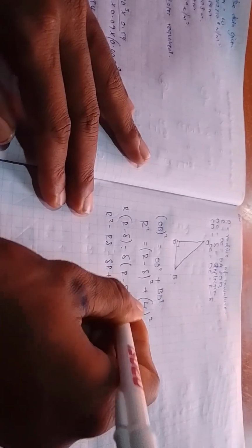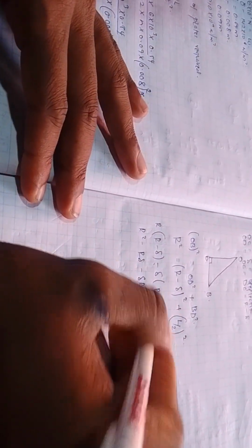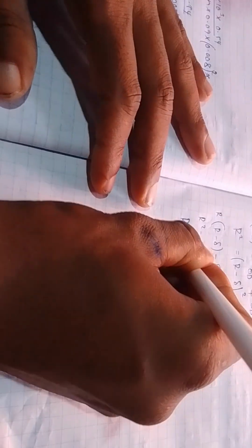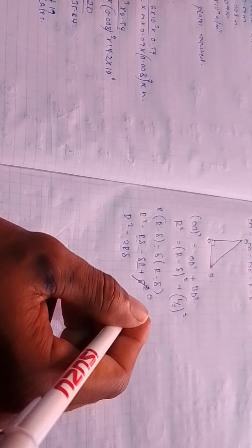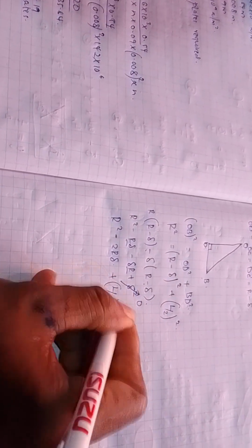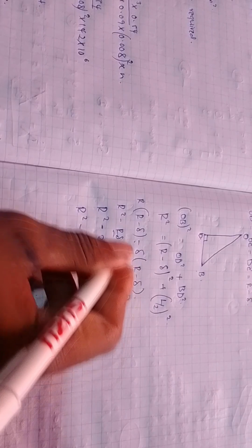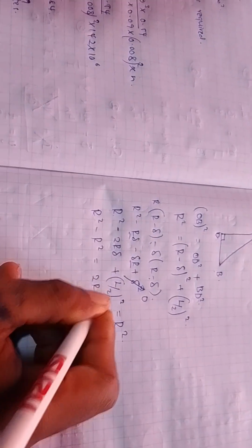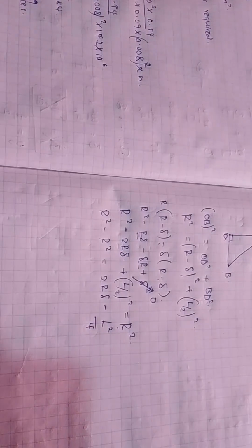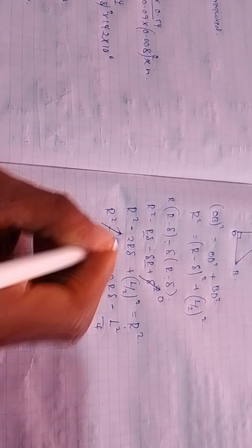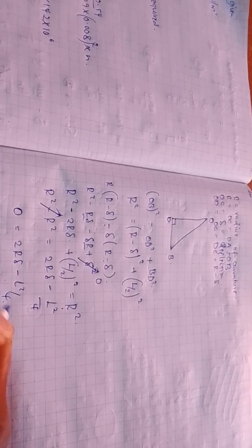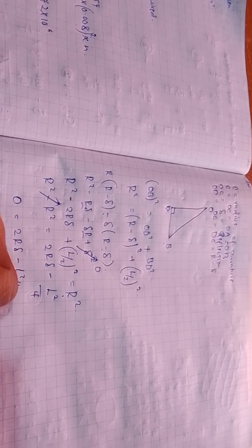Now, deflection squared is very small as it approaches 0, so we assume that it is gone. We are remaining with R squared minus 2R deflection, because those are like terms, plus L over 2 squared, equals R squared. Bring R squared to the other side, and it cancels out. So 0 equals minus 2R deflection plus L squared over 4. Take this to the other side: L squared over 4 equals 2R deflection.